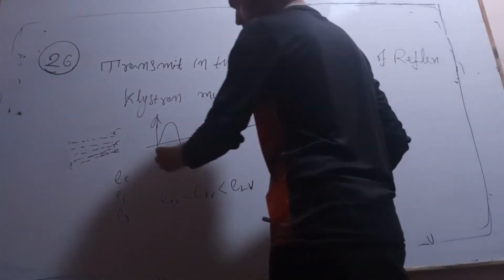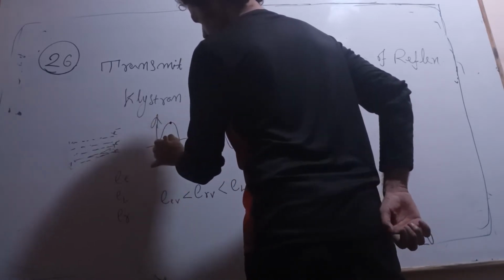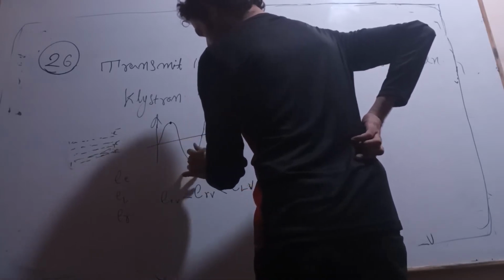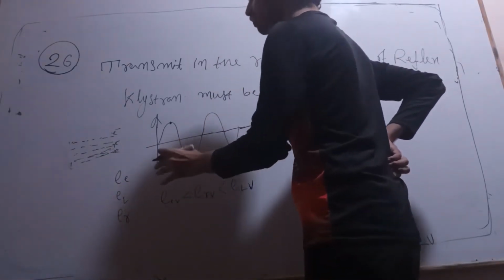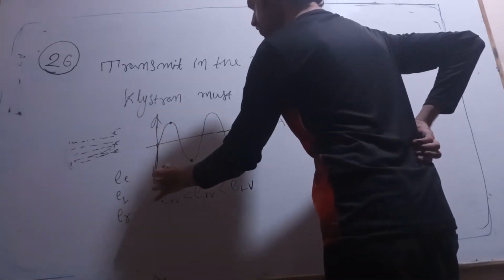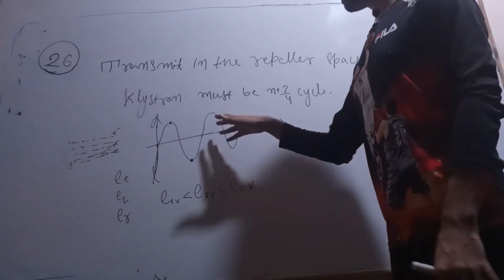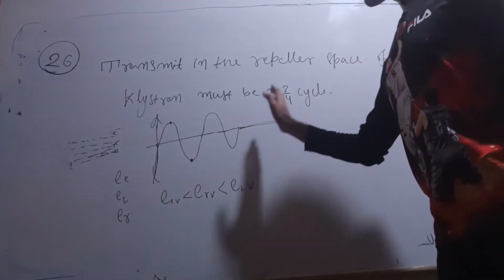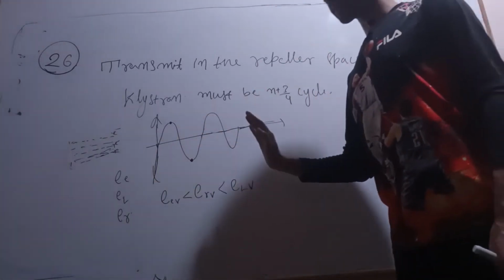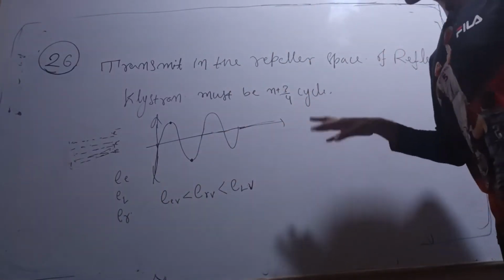If we superimpose these electrons in such a way that here is maximum retardation, because our ultimate aim is to retard this electron. During retardation the velocity of the electron decreases, the kinetic energy of the electron decreases, and hence the energy of the electron decreases, and all that energy is transferred to the RF signal.